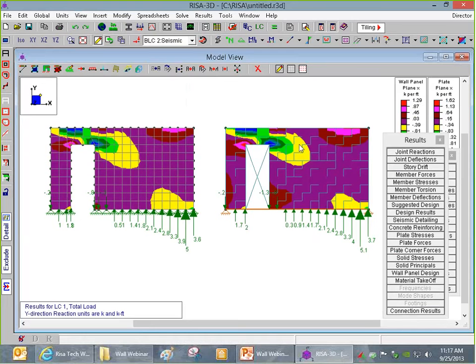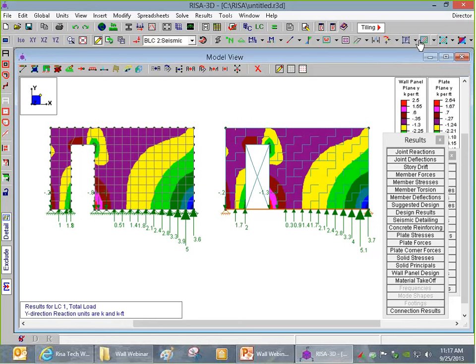If I take a look at the forces in the local X direction, this would be in the lateral direction. We can see they're all very similar here, and of course if I flip it over to Fy, everything matches up pretty closely. So you can see it's very easy to work with that within the walls. Now, of course, the contours are only going to give us relative rough numbers to see in this case. These are really ballpark figures. They're not exact numbers.